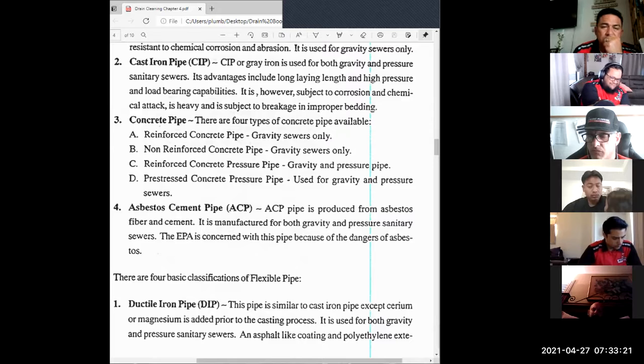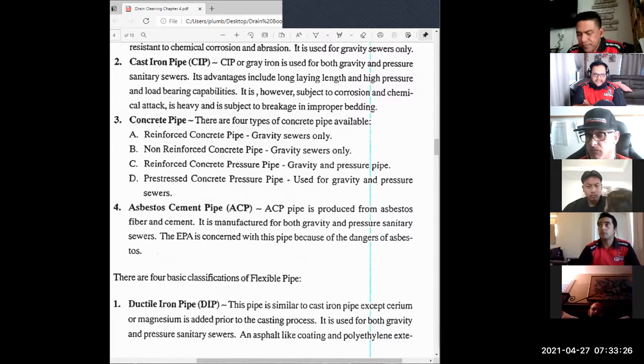So when you do dig up a sewer line that is asbestos, a lot of guys get very afraid of how to deal with it. My way of dealing with it is to just soak that thing with water, because it's the dust, the plumes of dust that you get from asbestos pipe, that is dangerous for you. You breathe those fibers in. Just soak that pipe down as you're dealing with it, and try to keep that dust down from that pipe.